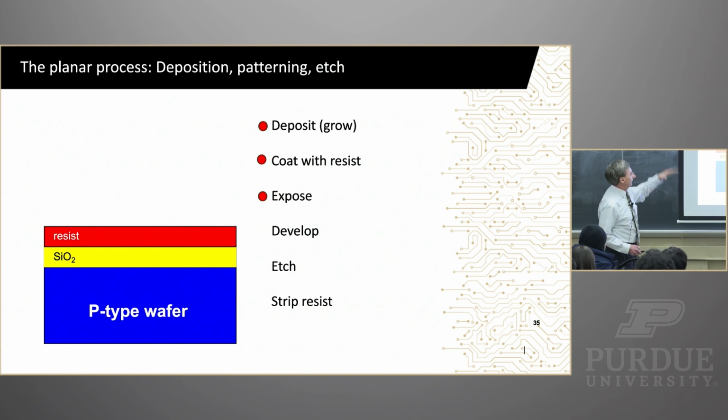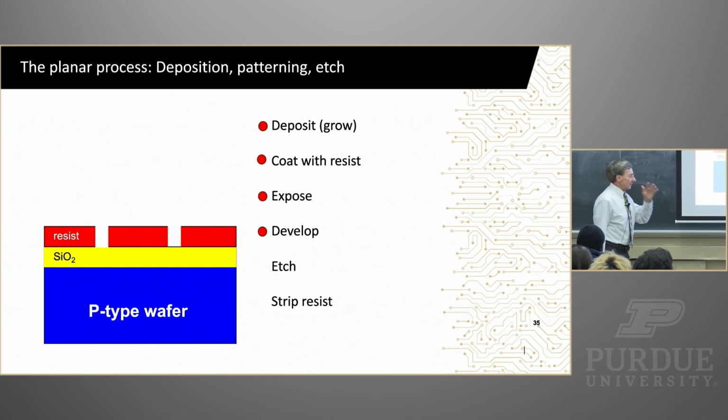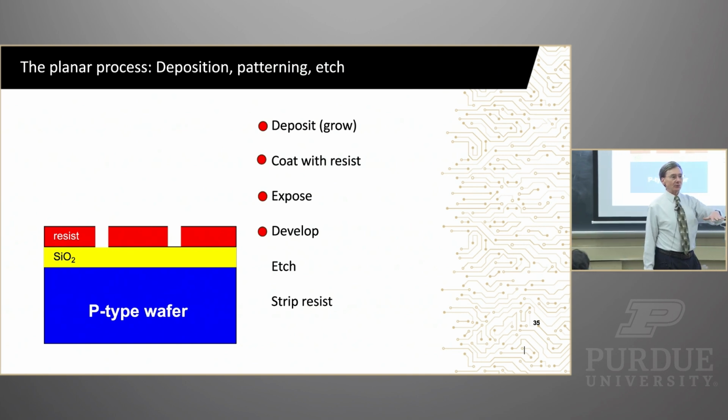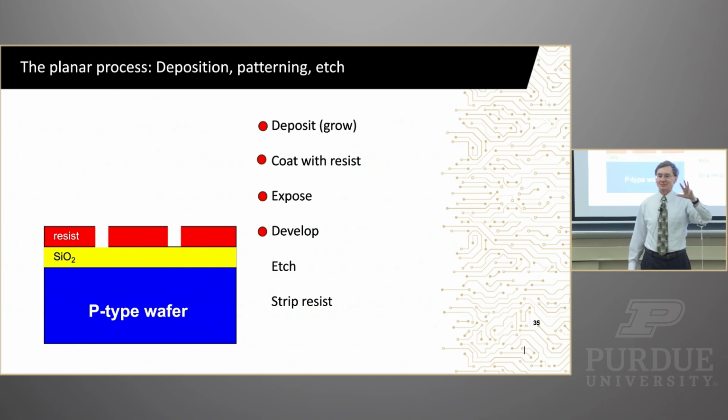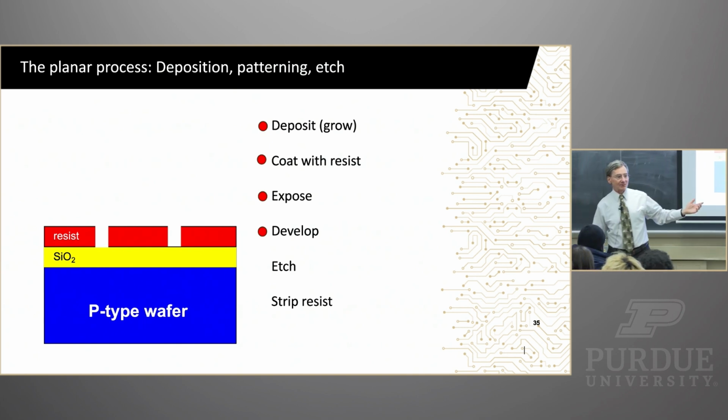So you now take the mask away, and you put it in a chemical that will develop it. You've modified some regions of the resist, and you can now develop them away. So you open a hole in the photoresist that matches the pattern that was on your mask. Whatever pattern you had on the mask now gets transferred into the wafer. Magic, right? Well, that's half the magic. The other half of the magic is now you do something with that photoresist.